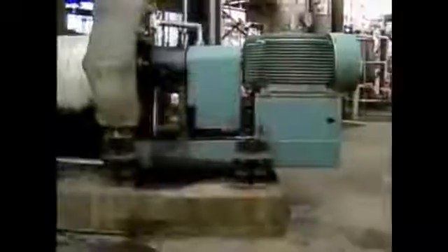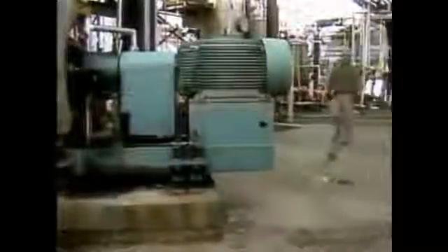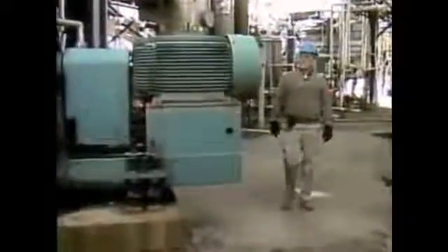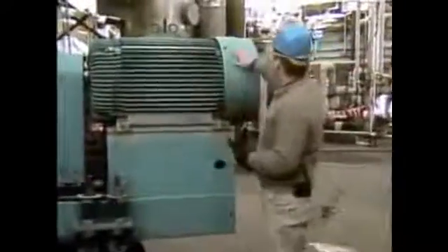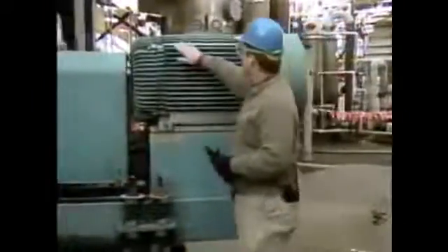It could also indicate a lubrication problem or improper alignment or clearances between parts. While some problems have distinctive sounds, others simply produce excessive noise or vibration. Checking for unusual vibration is a common part of a pump inspection. A quick check can usually be accomplished by carefully touching the motor and the pump with a bare hand.